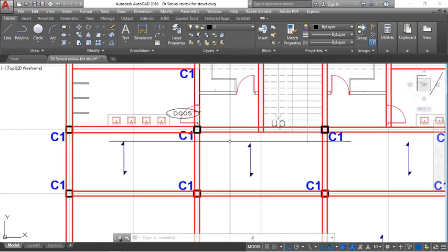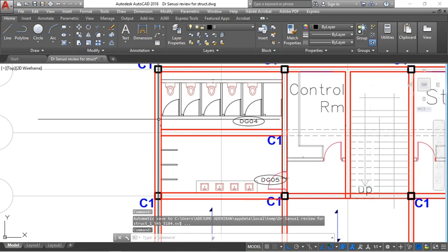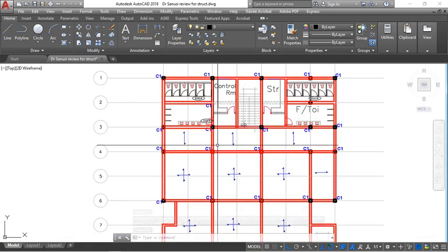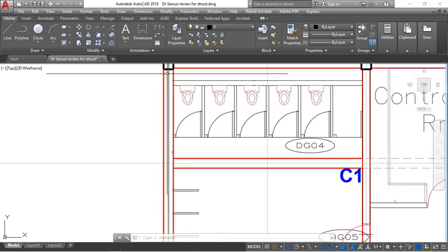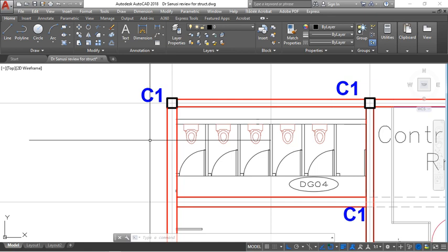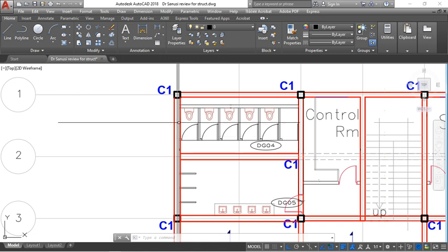So most times, if you are designing a pile and pile cap kind of foundation, the next thing for you to do is to provide tie beam, then provide your ground floor. That means you have to suspend your ground floor. So what it means is that your tie beam will be spanning depending on how you have determined your finished ground level and then finished compound level. Then you know how to place these beams at whatever level.